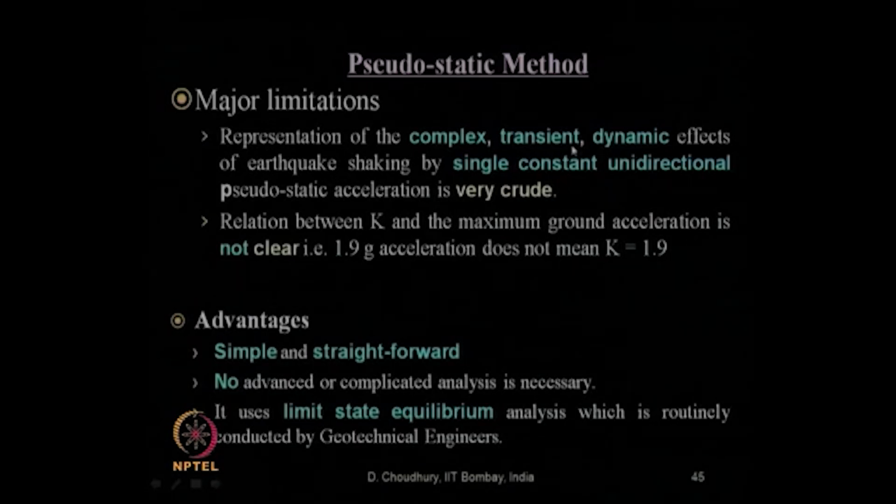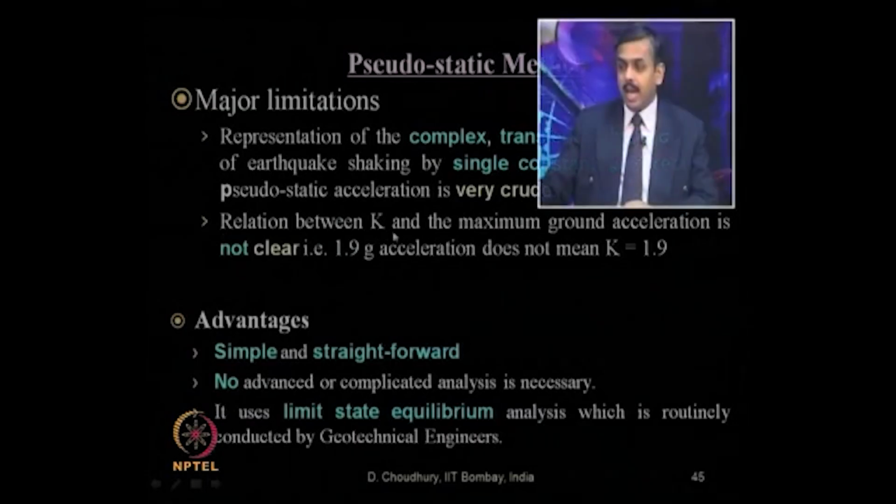None of these dynamic properties are considered in this pseudostatic method, only a single constant value is used. So, that is why it is a very crude estimation of the dynamic nature of the problem in a quasi-static manner. Also, the relation between the k and the maximum ground acceleration is not clear.